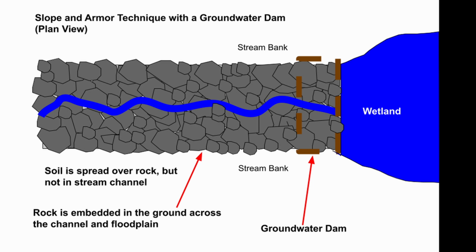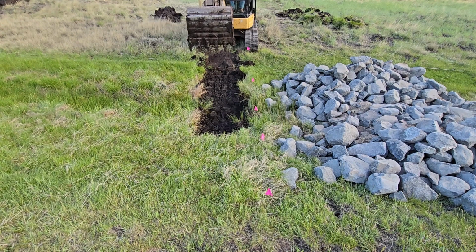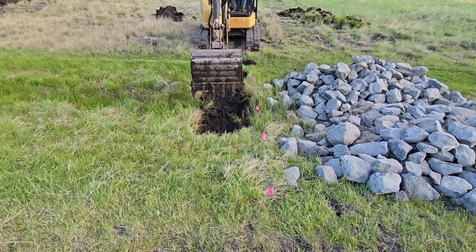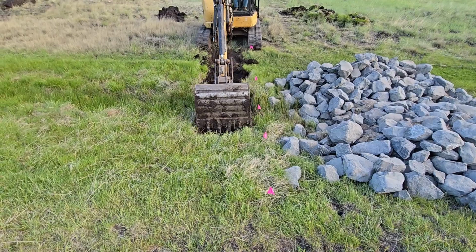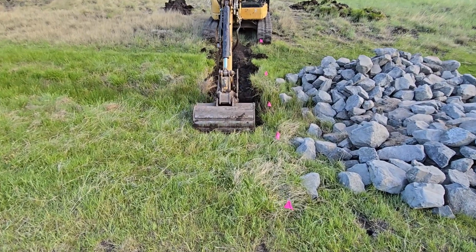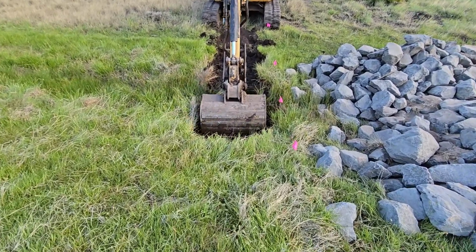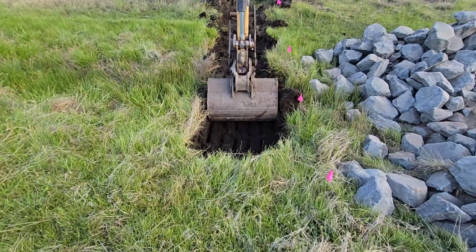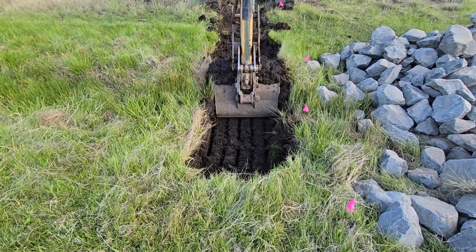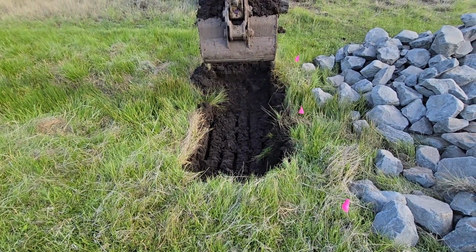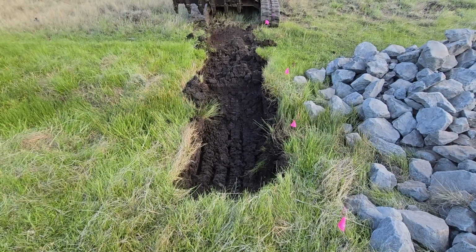Don Smith begins the restoration of this wetland by digging a core trench perpendicular and across the floodplain of the dry stream. The pink wire flags mark the lower edge of the trench to be dug. The wheel loader placed the rock next to the trench so it could be used to armor the spillway to prevent head cuts from forming.